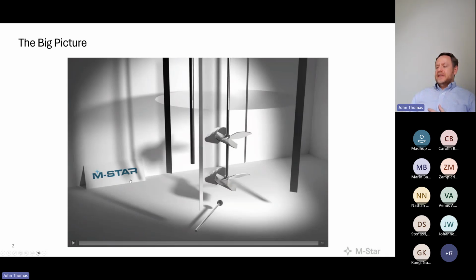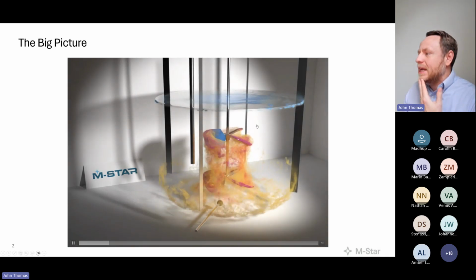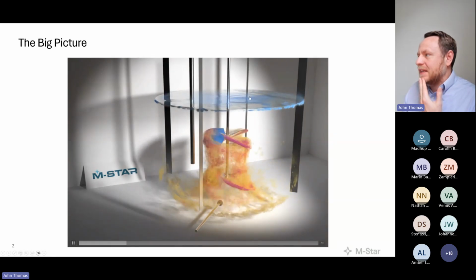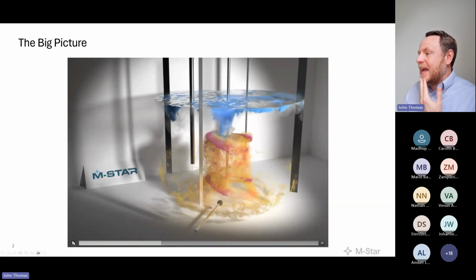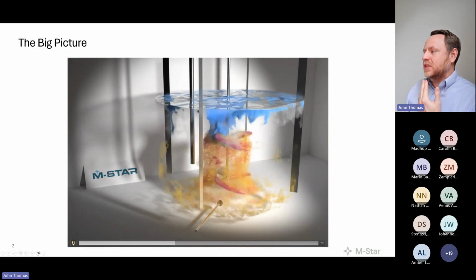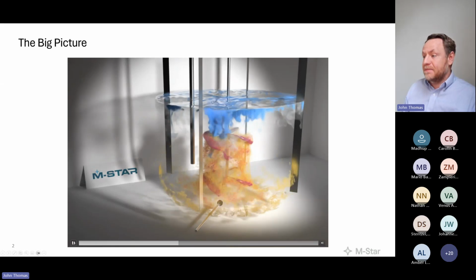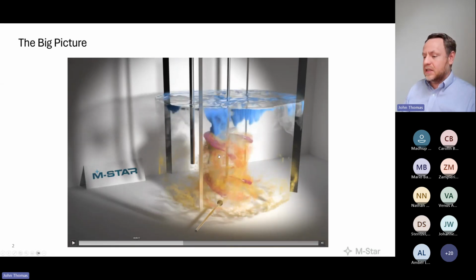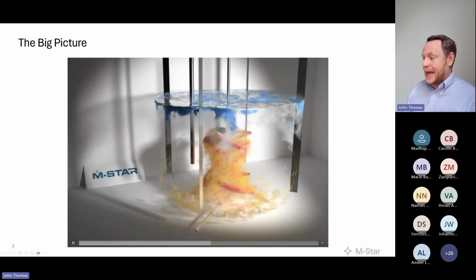So again, the big picture is this. We're talking about systems where oxygen, or any dissolved gas, has a few ways of getting in the system. Option one is via the free surface, where we have some sort of concentration maintained in a headspace, and just due to the agitation of the fluid and the convective transport processes, which I'll speak to today, along this free surface, we can whisk oxygen or other gases from the headspace into the aqueous phase via convection at the free surface, okay? In a non-sparged system, this is the means by which dissolved gases get into the aqueous phase. And so foundationally, this is a transport mechanism that's relevant in systems where we don't have sparged gases.